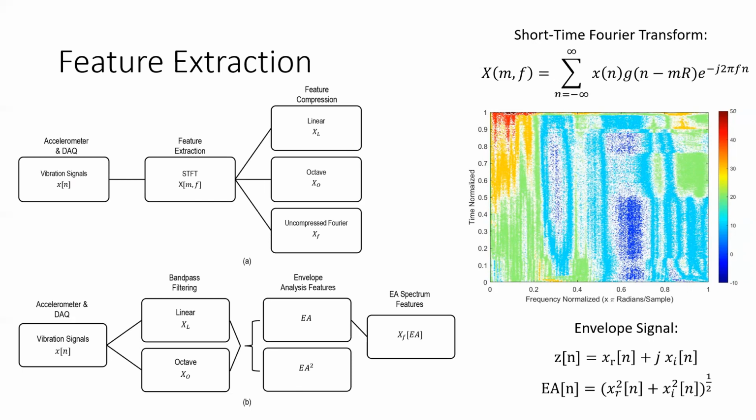For this particular dataset, bearing signals are acquired using 2 orthogonally placed accelerometers fixed to the horizontal and vertical axis of the bearing's external race. 7 bearings were run to failure at operating speeds of 800 RPM and a load of 4,000 newtons was applied. Signals were recorded every 10 seconds at a sampling frequency of 25.6 kHz until failure was detected with the signal amplitude surpassing the value of 20 G.